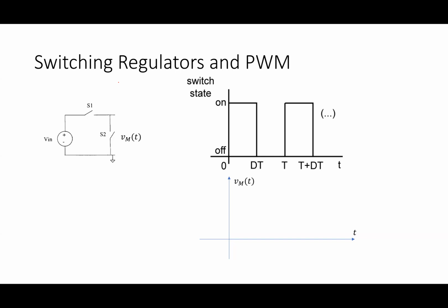So with those things, right, what do you do? You put little tiny voltages into those. So you put 10 millivolts in and you get 10 volts out and all kinds of good stuff, right? That's not the way we operate these transistors, right? It's the region they don't talk about. It's called the linear region. I'm not going to talk too much about the MOSFET piece of this. But basically, if I take a MOSFET and I take its gate to source voltage and I make it very high, it goes into what we call the linear region. And when you do that, the switch looks like a short circuit when it's on. Right? Forget all this stuff with gms and all that stuff. Basically, this is for the idiot mode of operation. Guys like me like to operate here.